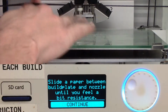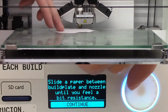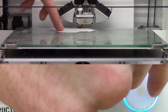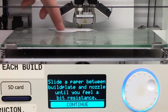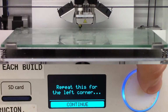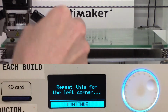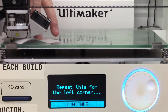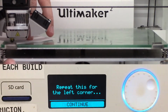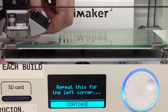Now we'll take a piece of paper, we'll slide it underneath the printer nozzle in between that and the tray, and we'll rotate the wheel again until we feel a bit of resistance between the printer nozzle and the piece of paper. You don't want it to be too loose because then your part will peel off of the tray, and you don't want it to be too tight because then you risk damaging the printer nozzle as it drags across the surface platform. Now we're going to repeat the process in the front left, and again we're not going to use the wheel, we're going to use the set screw to get that similar form of moderate resistance between the nozzle and the paper.